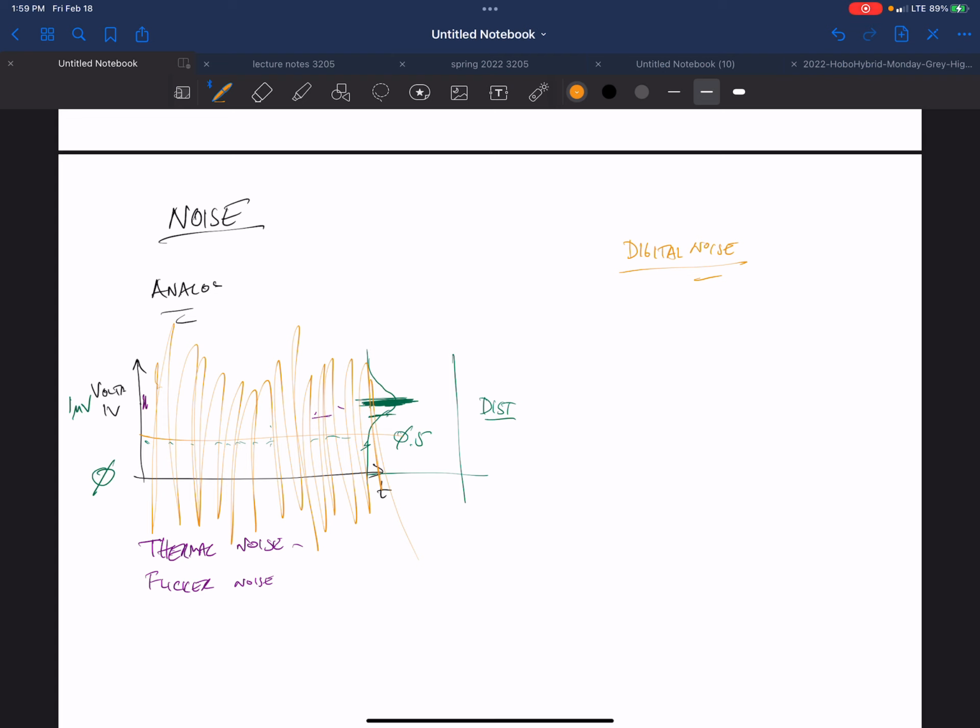But now imagine if you have your 20 billion transistor circuit, it's getting clocked at 5 gigahertz. There's cell phones all around you. There's the power supply itself off the wall. There's you and your 10 million of your closest friends on that same power network, and people are turning stuff on and off. The refrigerator next door is going on and off. All of this shows up as glitches in your power supplies and in your grounds typically.